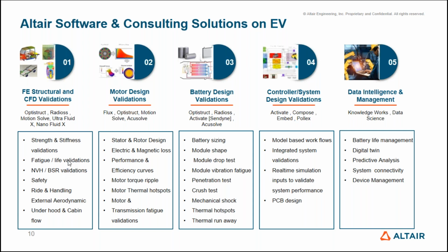The next stage is the motor design and validation. We have a dedicated platform named Flux solver, where we have Flux Motor as a motor design and simulation tool, where you can do the stator and rotor design, and calculate the electric and magnetic losses. Further, you can improve the motor performance in terms of efficiency.